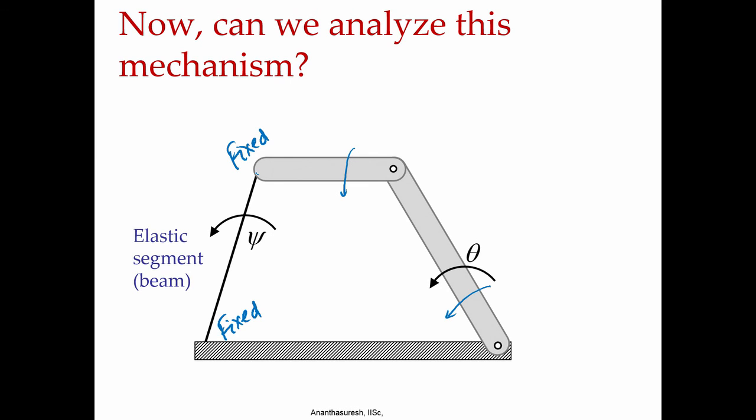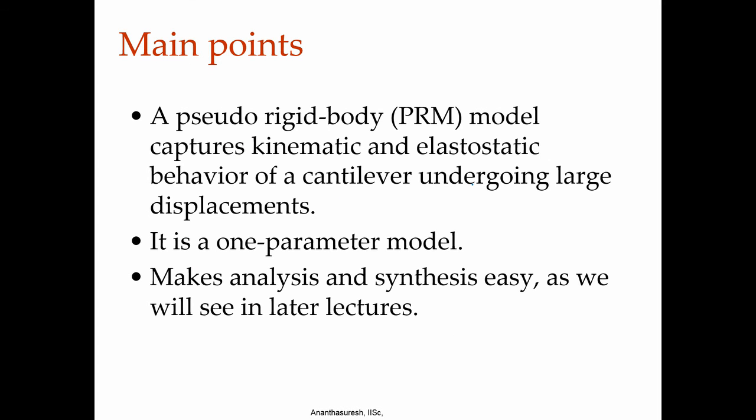So, the fixed one is difficult to deal with in the pseudo rigid body modeling concept, but we will get an example to see how close it will be, making an approximation, right. Just forget about the fact that it is fixed, take 0.85 as a characteristic factor or some other value, and see how close we can get if we were to analyze it using, let us say, finite element analysis and compare it. So, we will look at these few examples in the next lecture.